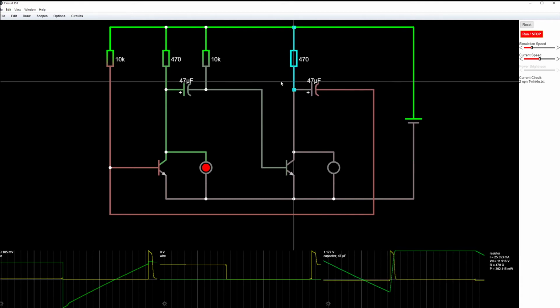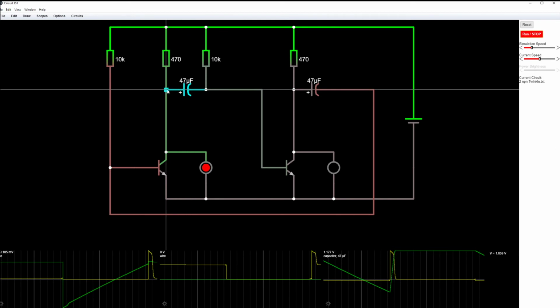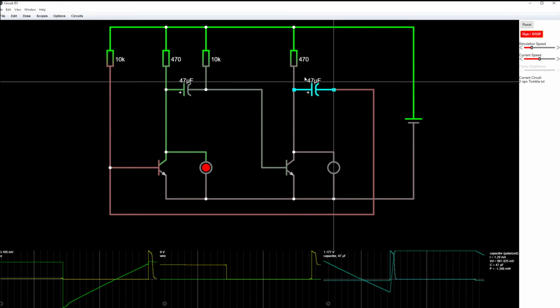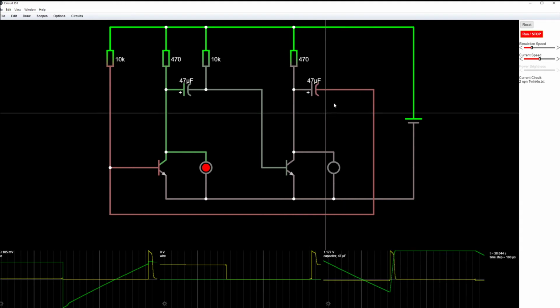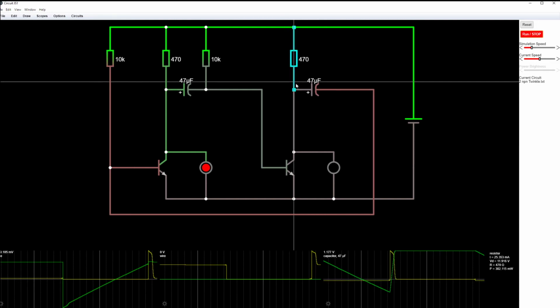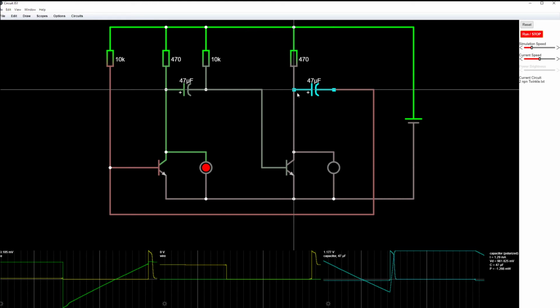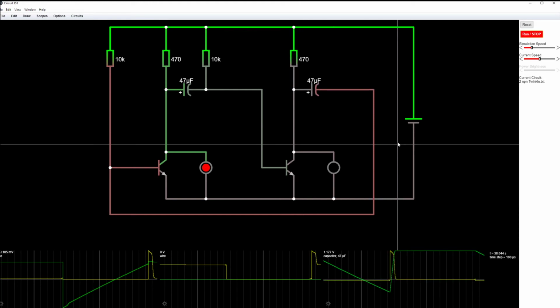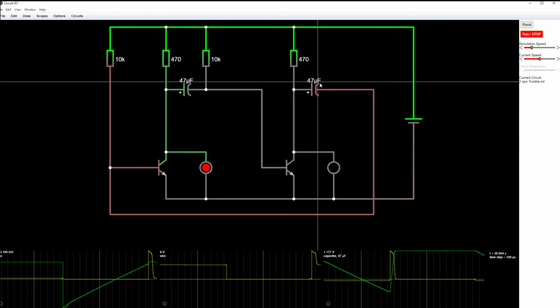But remember, the capacitor is saying it always wants to have that same voltage difference. So usually we can think of it, like in this case over here, as this part being 1.1 and this part being 0.6. So we can know that's a voltage difference of 1.1. But it works the same if the left side of the capacitor is at 0, then the right side of the capacitor has to be at minus 1.1. And so that's what's happening in this system, because we're just saying this is producing a 1.1 volt difference across this capacitor. As soon as we say, well, the original voltage here isn't actually 1.8 volts, because we've connected it, it's actually at 0 volts, so this has to be at negative voltage.